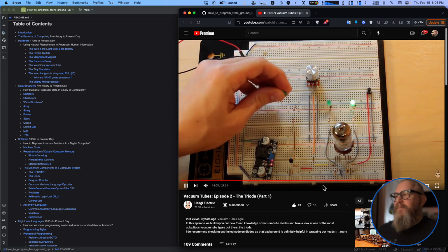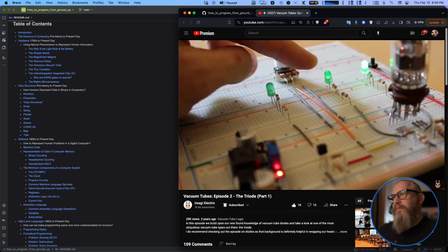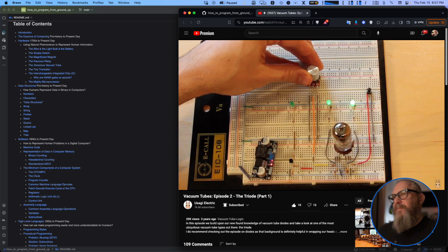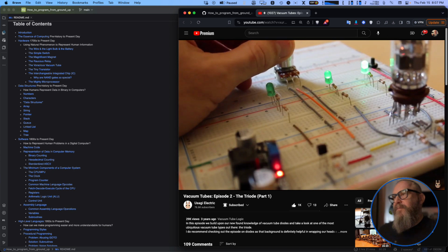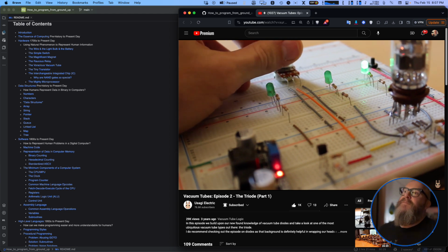All right, so what about this transistor? It's set up pretty much exactly the same, so we should see a pretty similar result, right? Here we go. Let's rotate the potentiometer. You can see that the triode LED is starting to illuminate, but the transistor LED isn't on yet. The triode LED is getting brighter and brighter, but this LED is actually still off. If I go a little bit further, whoa, look at that. The LED came on to full brightness with not even a 16th of a turn. If I go back, it turns right off again.